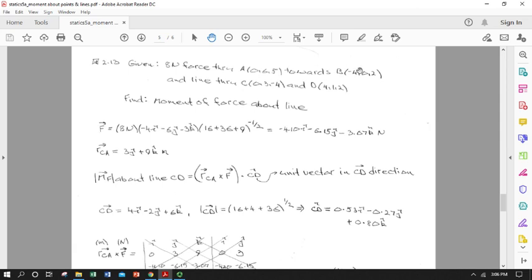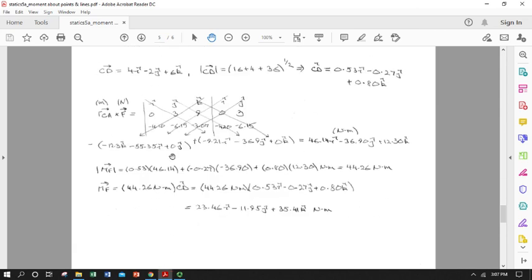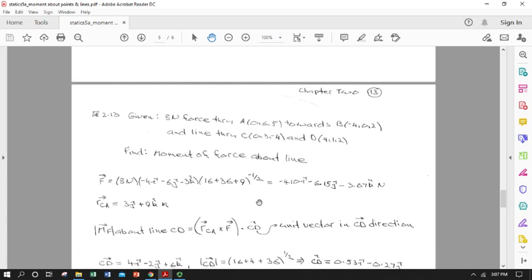Except this time you're going to use all vector algebra. You won't have any opportunity to do geometry as much on this. So you'll construct your line, get its length with Pythagorean. There's your line of force, multiply by the magnitude, and get a radius from either of these points to either of these points, and calculate a moment around whatever point on the line. You're going to need to get a unit vector for this line. So you'll start by getting a regular vector for the line. Here's a regular vector for the line. I get its length, I divide, and now I get a unit vector for the line. And I can basically get my dot product, multiply by the unit vector again, and get a moment vector, the only component of it parallel to that line. So you can go through these steps on your own and use this as a self-check if you'd like.